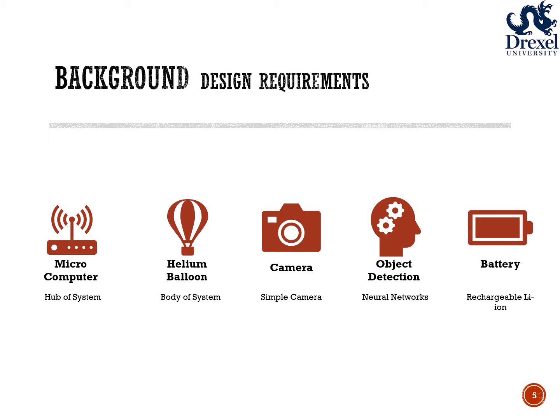Some kind of object detection technique, something like an open source detection algorithm such as neural networks would work well. And finally, a power supply to feed the whole system. A small rechargeable lithium-ion battery would work well because it has the output of required 5 volts, it's lightweight, and provides enough to sustain the system during testing.